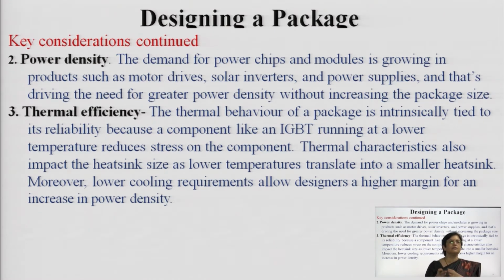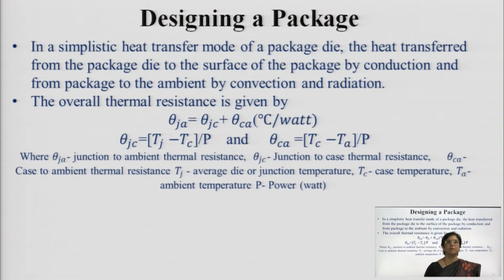The thermal characteristics also impact the heat sink size. If you have low temperature, you can have smaller heat sinks. Moreover, lower cooling requirements allow designers to make use of that space, because that space can be utilized for more devices, or you have margin for increasing the power density. So if you don't require any heat sink, then you can incorporate multiple devices having multiple functionalities.